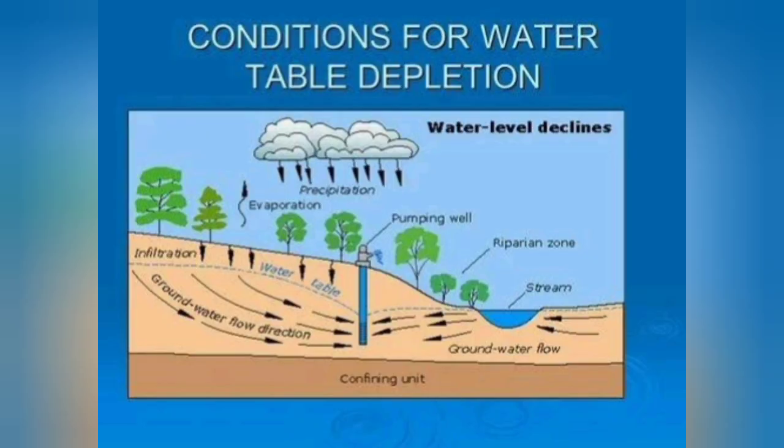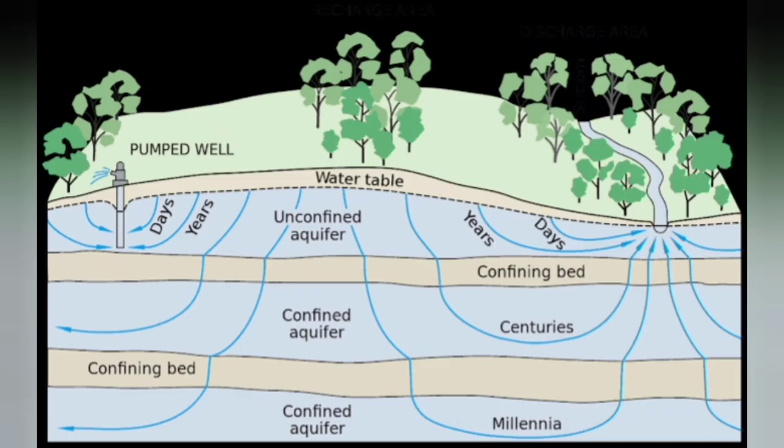Silt may be defined as the content of undissolved solid matter, usually measured in milligrams per liter, which settles in stagnant water with velocities which do not exceed 0.1 meter per hour. To obtain still clearer water with only 10 to 12 milligrams per liter suspended solids, further addition of flocculants and frequent agitation of the water must be resorted to.